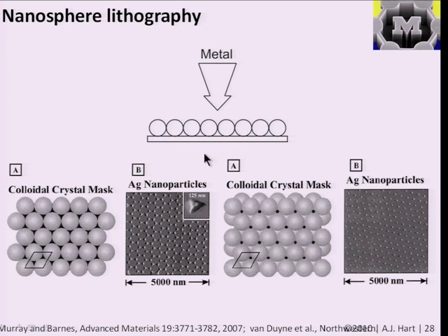It's possible to purchase these microspheres in a bottle dispersed in water. They have charges on their surface, so they're stable. So the spheres are, say, a micron in diameter. And because the spheres are a micron, the spaces between the spheres where you can basically see down to the substrate are a lot smaller. So you can then assemble this layer, deposit metal, say by evaporation or sputtering, and then lift off the spheres, and you're left with an array of nanoparticles, or you could say small islands of metal film that are in the sub-micron size range. In this case, maybe it's about 125 nanometers here, so it's about 1/10 the diameter of the sphere.